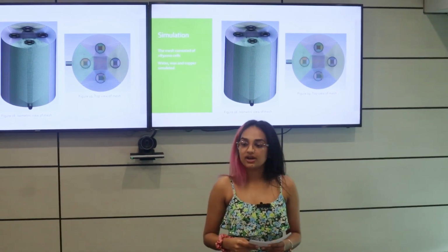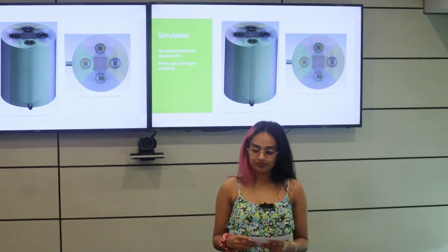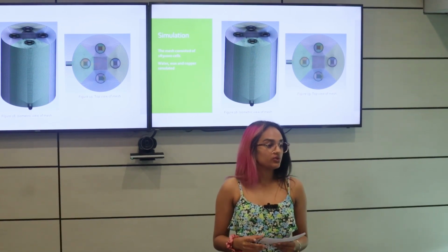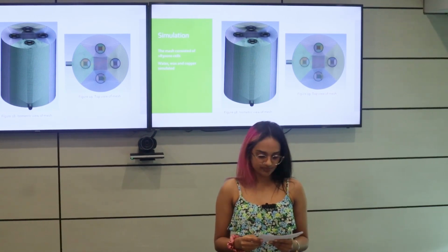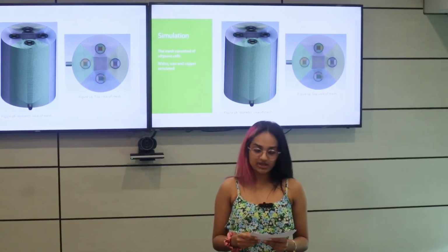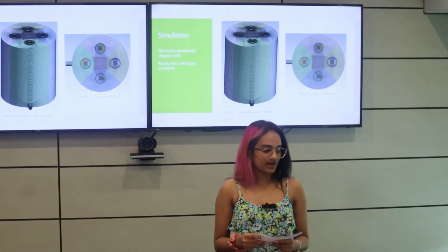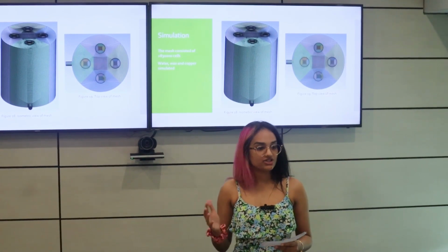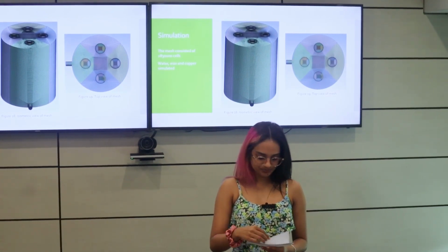It should be noted that only the wax, copper, and water was simulated in this model. It was decided to do this for the ease of calculations, as it will take less time to run the simulation. The model here is made to be adiabatic, meaning that there is no heat loss in the system. This assumption is valid, as due to the insulation that was put on the tank, the heat loss is expected to be minimal.